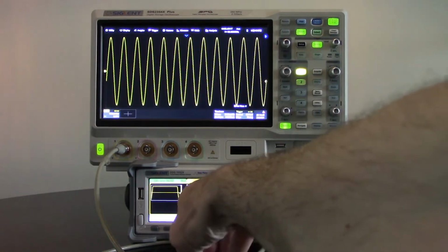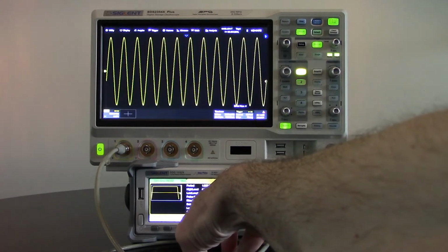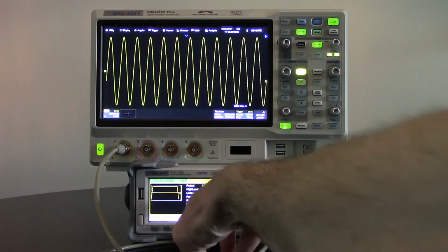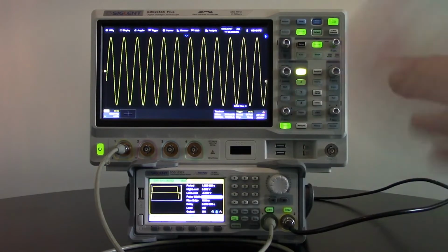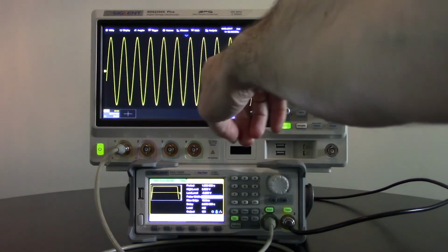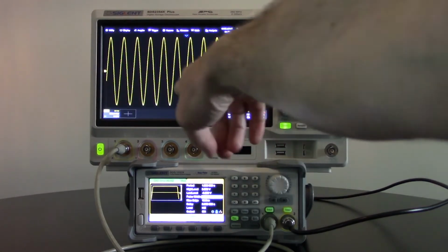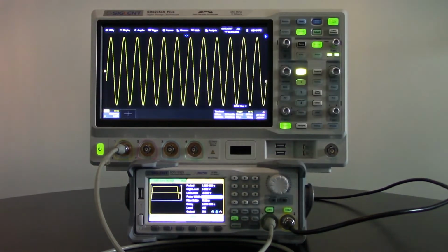So in this case, I've got a 1 second pulse, and for 984 milliseconds, the majority of that pulse is going to be high, but then 16 milliseconds is going to be low. That's equated to roughly 1 period. And you'll see on the scope display, about once a second, I'm seeing a 1 period drop in my amplitude. Now, if I knew exactly where it was, and I do in this case because we set up this experiment, it's pretty easy to find. But if I didn't know where it was, it may be very difficult.